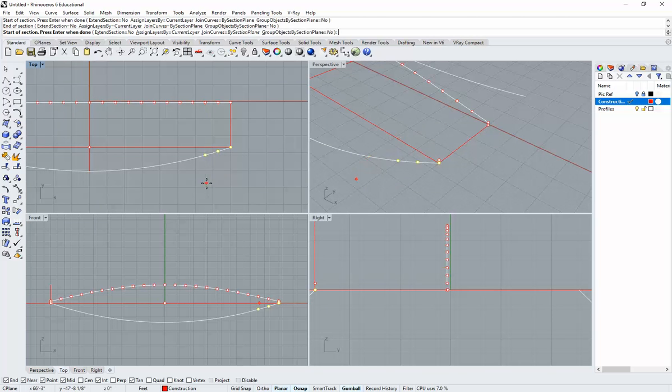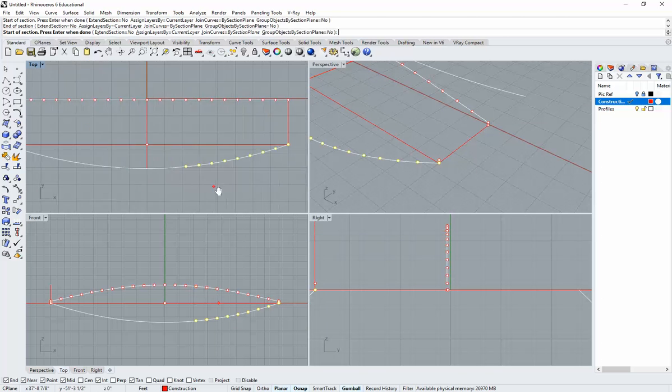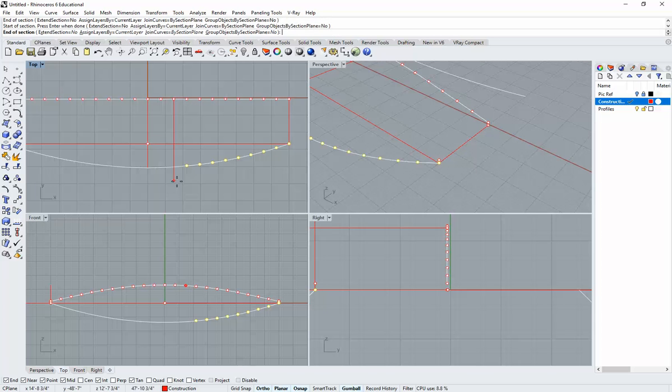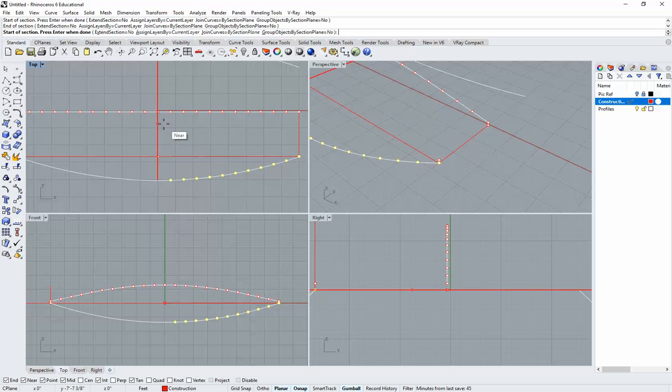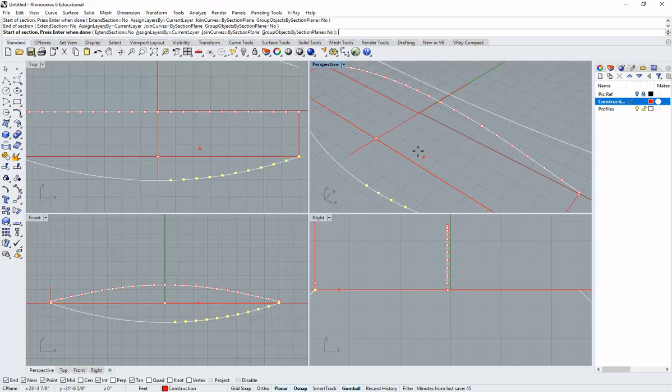And this is the way that I'm going to ensure that these points have a direct orthogonal relationship to one another from the middle arch to the end profile. Because if I run the divide command on the outer profile, the white one down below on the screen, it's likely that those points won't line up because they're not the same length. So that's our center.